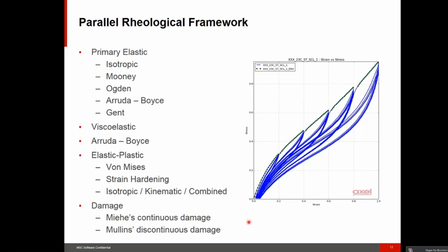So for these types of materials, it's important not just to do a uniaxial tension curve, actually best to do cyclic data, cyclic testing at different strain rates and at different magnitudes of the stress so that you get a full series of data. And we get this data not only for uniaxial tension type behavior, but also for biaxial data.